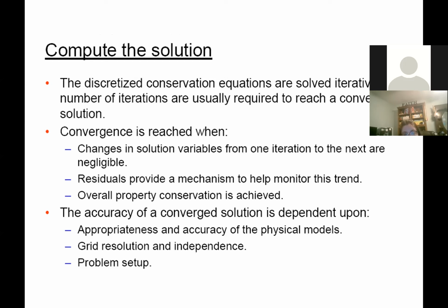Okay, for the flow field, there's only one solution. So your task is, if that's the case, that's a problem you are going to simulate. The task is just to find out the set of the solution for the field. Okay, it doesn't change with time. So if that's the case, when you start the simulation, it needs iterations, because the boundary condition won't immediately propagate into the entire domain. It takes iterations.